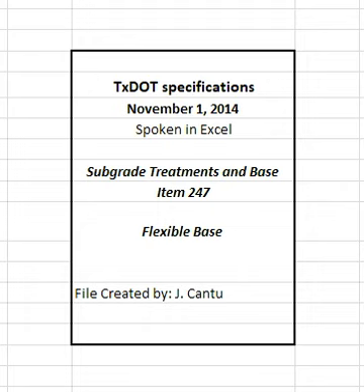The engineer will determine roadway density and moisture content of completed sections in accordance with TX 115E. The engineer may accept the section if no more than one of the 5 most recent density tests is below the specified density and the failing test is no more than 3 pcf below the specified density.